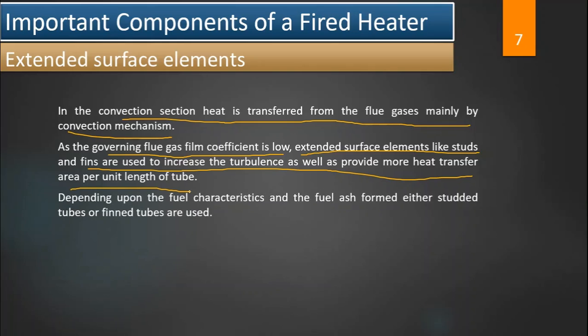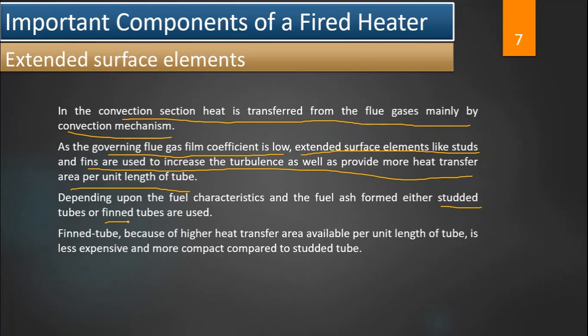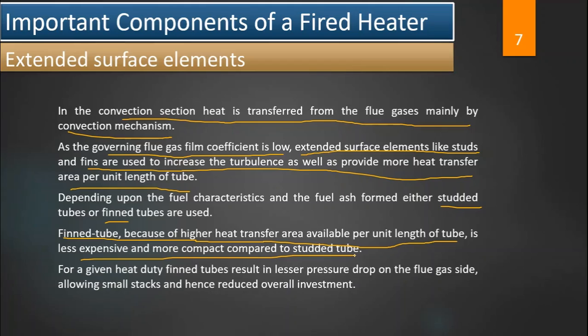So either go for the struts or you can go for the fins type. Both are used, but fins have their own advantages. For example, they have a high heat transfer area available per unit length and are less expensive and more compact compared to the strut tubes.